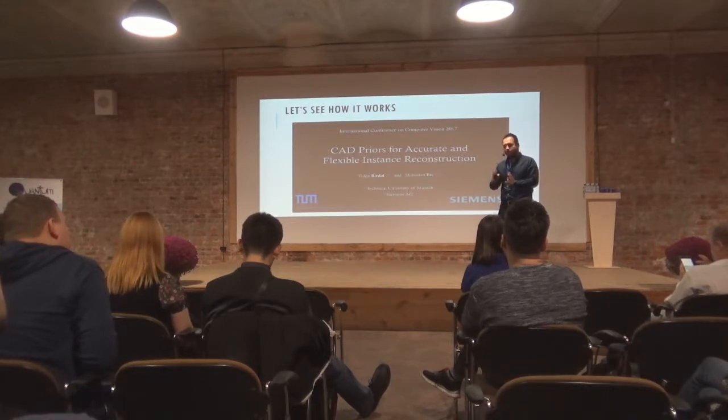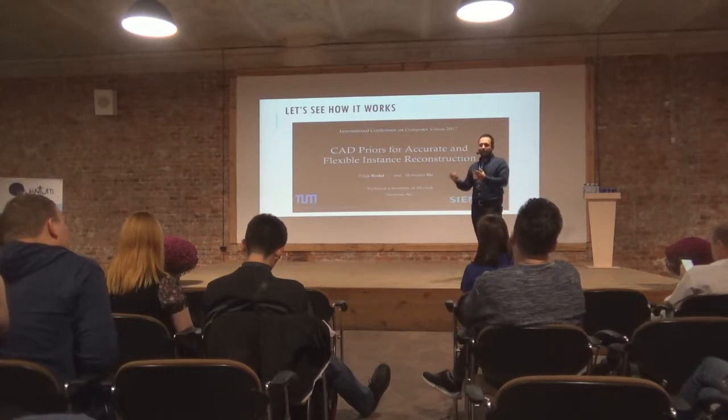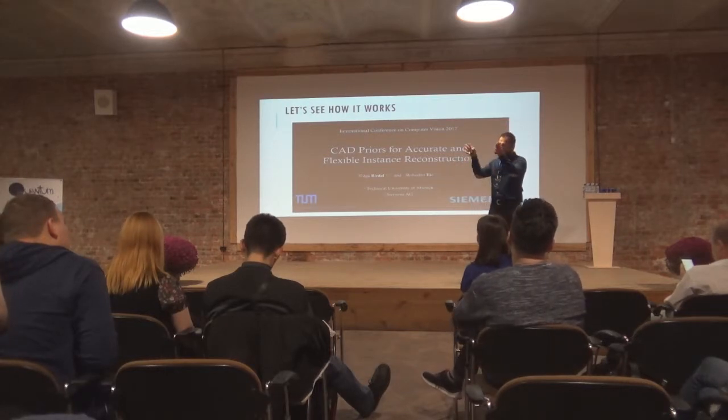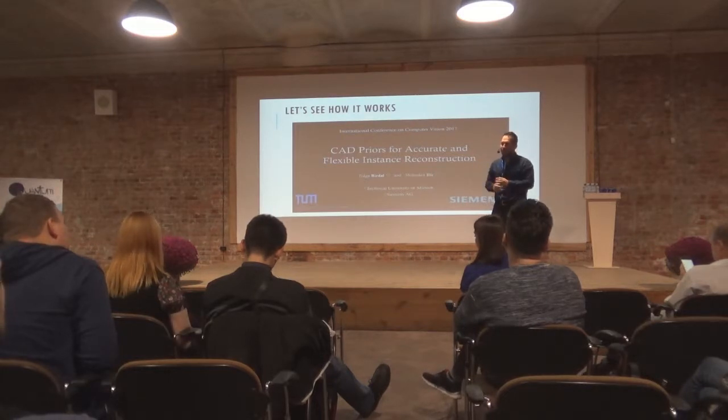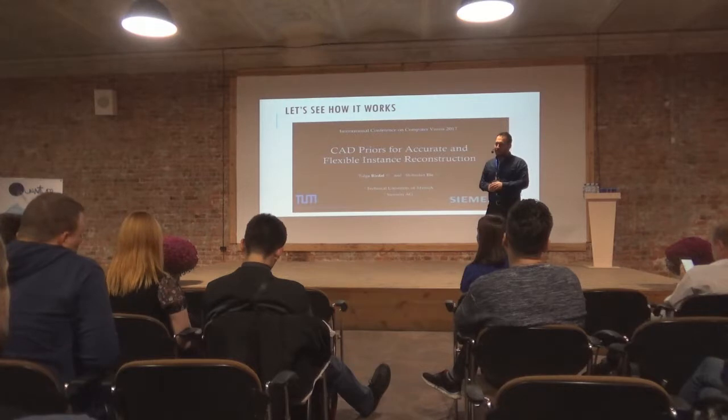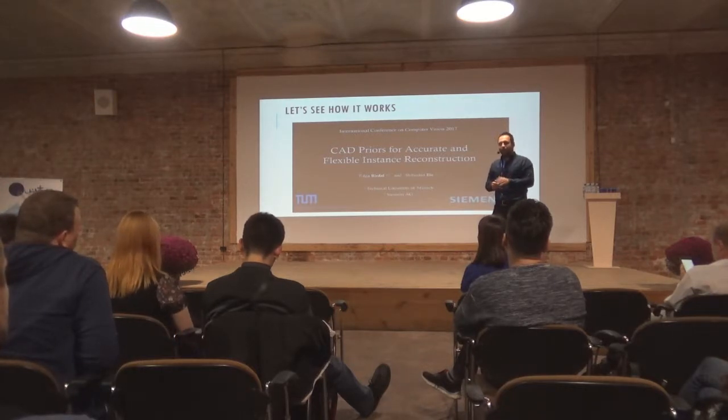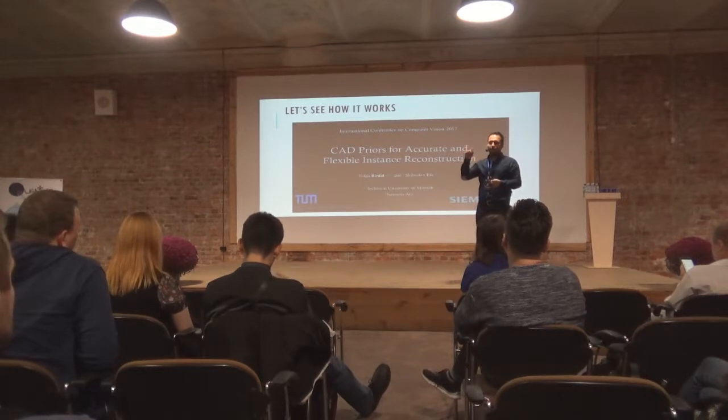So the laser scanner accuracy is 1 millimeter in 10 meters if you have the highest quality, which means you wait for 2 hours. Not to wait for 2 hours, they just go close by the object and capture a constrained scene with higher quality that takes about half an hour. And that results in something like 0.7 millimeters. And this added 0.3 or 0.5, whatever, is the error I make in registering these things.